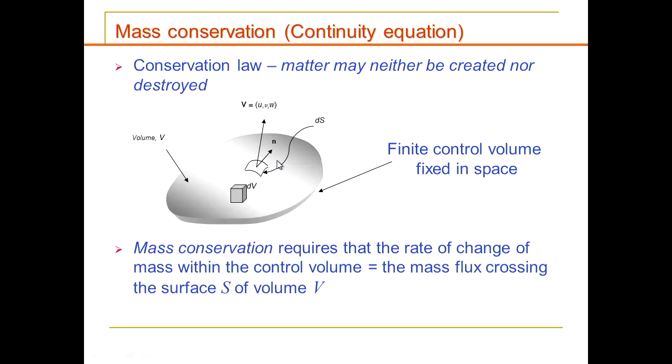So the idea is by invoking the mass conservation law, we know that whatever change for this fluid element in terms of mass equals the summation of outgoing mass flux minus the incoming. Anyone don't get that? Should be simple enough, right? But how do we put it in terms of formula? So easy, like first thing we know from the left-hand side is dm/dt, because that's your rate of change of mass, isn't it? So what about mass flux?